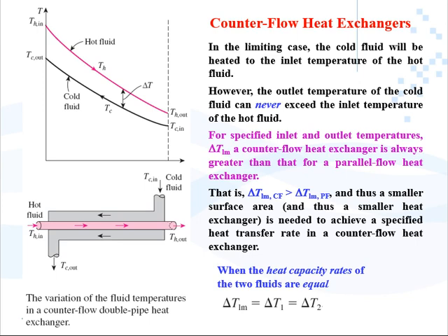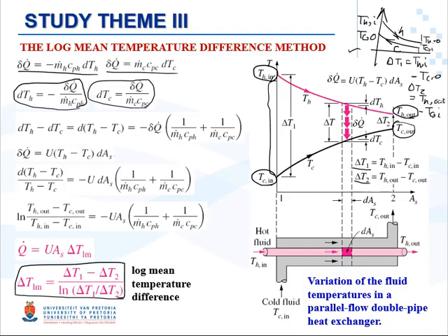But there is a big difference here. If you compare it with the parallel flow one, you see that the outlet temperature of the cold fluid cannot be higher than the outlet temperature of the hot fluid. They can be close, but they can't be exactly the same or even higher.